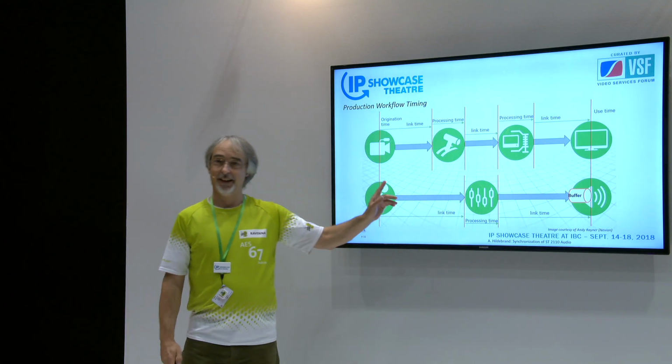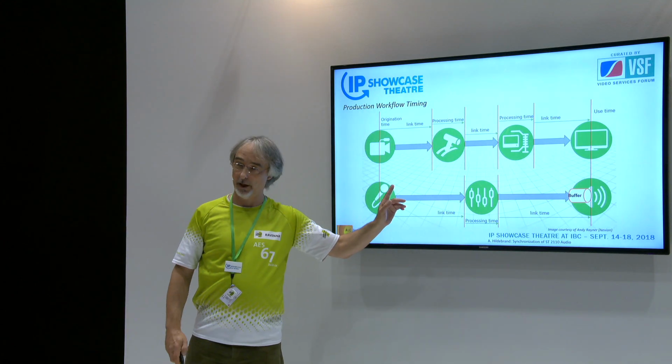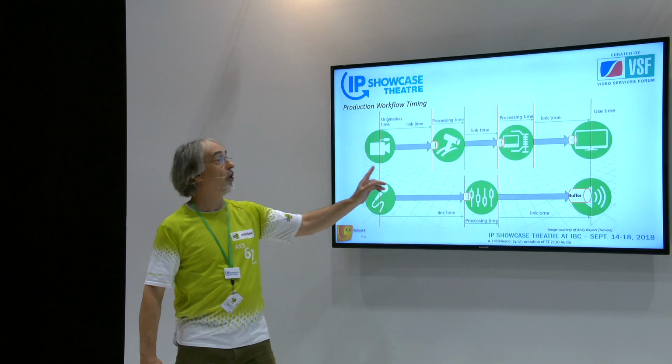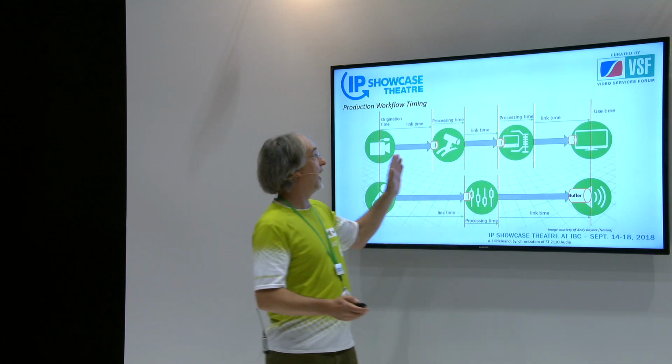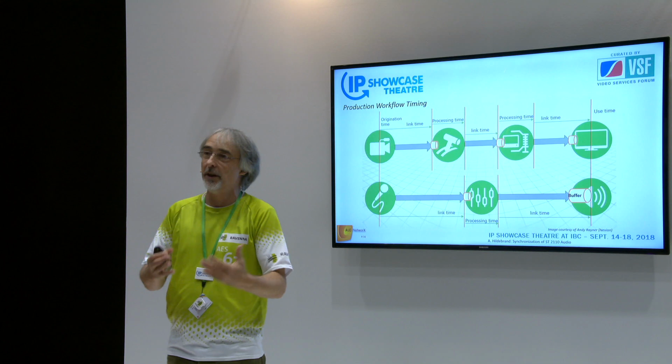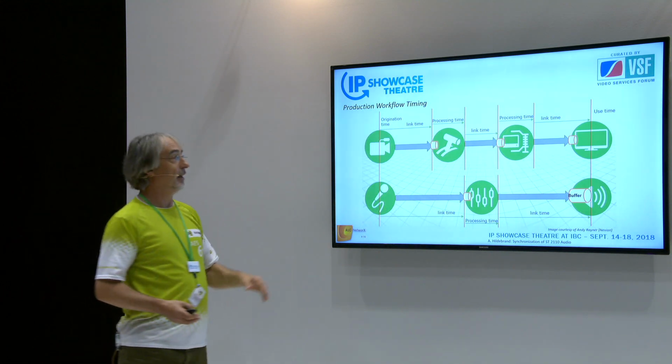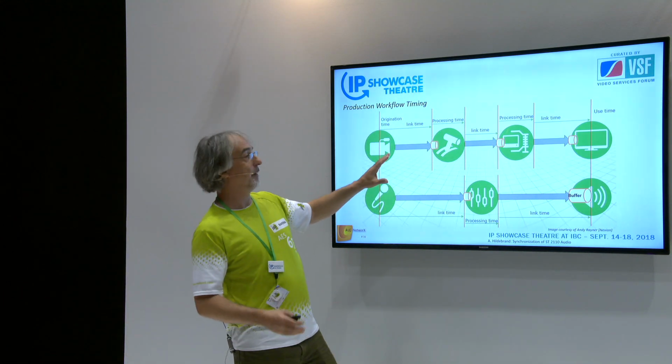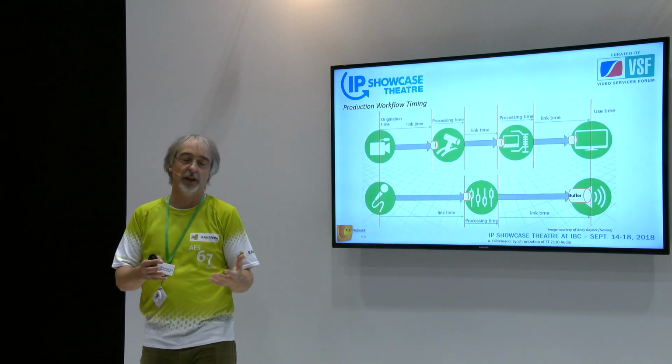Actually, in our AoIP or video over IP environment, all these devices have to have buffers because packet jitter is appearing everywhere. So any stage which is receiving an IP stream needs to have a packet buffer. How large this would be is nothing which is specified in the standards actually.